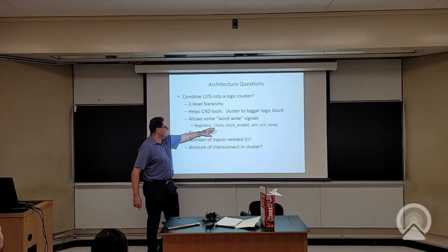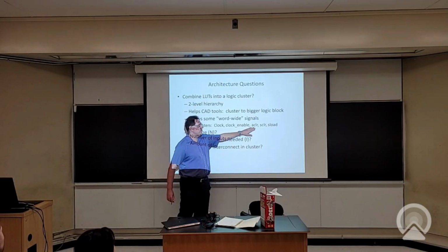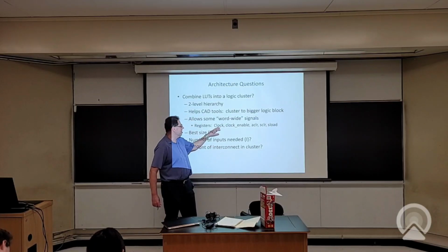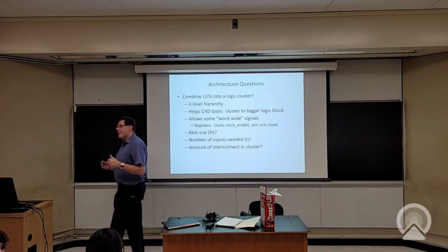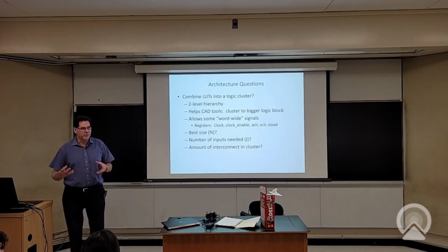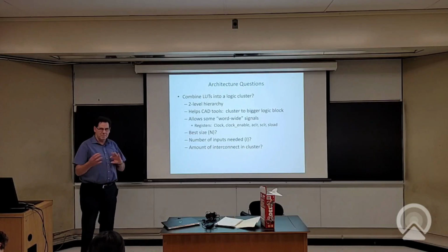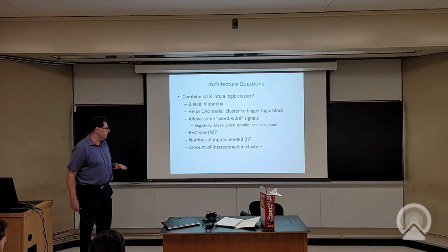So in disciplined designs, the clocks usually have quite high fan out, at least most of them. And these signals have pretty high fan out too. So they make sense to group together in a physical structure where you don't need so many muxes, et cetera. You're sort of a broadcast within the logic block.